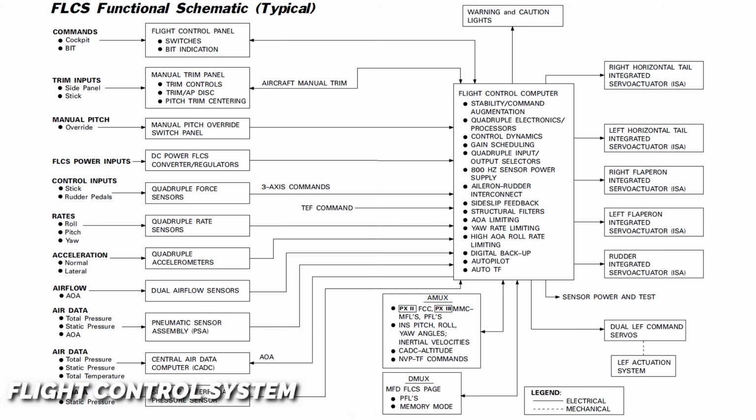The FLCS is a computer-controlled, 4-channel, fly-by-wire system. It has 3 operational modes: standby gains, takeoff and landing gains, and cruise gains. The normal mode of operation is cruise gains. The FLCS is in cruise gains when landing gear is up, alt flaps is in the normal position or extend above 400 knots, or air refuel is in the closed position or open above 400 knots.